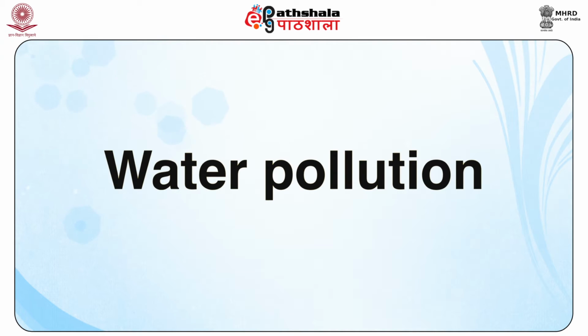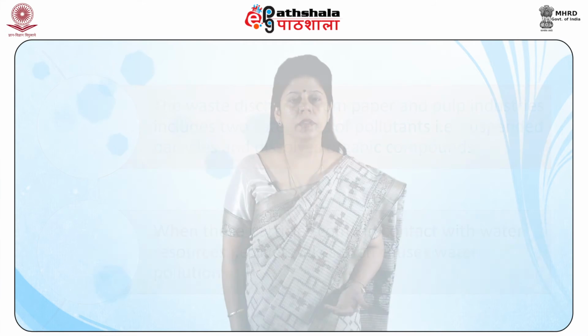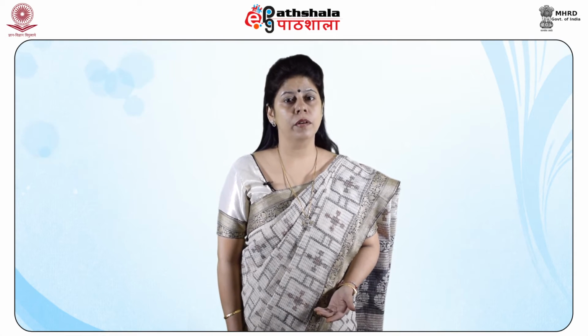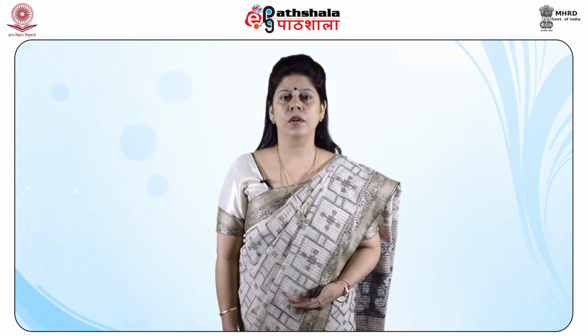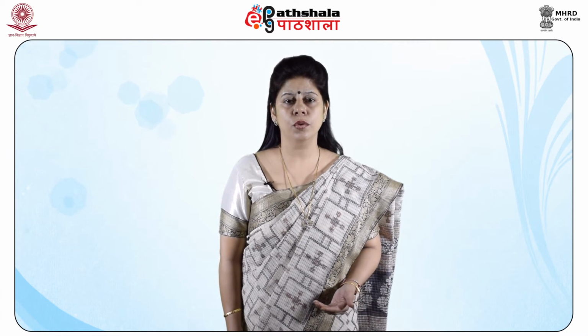The second problem is water pollution. The waste discharge from the paper and pulp industries includes two categories of pollutants, that is suspended particles and dissolved organic compounds. When these particles come in contact with water resources, that is rivers and lakes, they cause water pollution. The suspended matter present in the paper mills is in the form of particulates of wood, fiber, filling and coating material, whereas the organic pollutants, when acted on by microorganisms, are converted into inorganic compounds and reduce the oxygen level. Also, inorganic materials such as chlorates, chelating agents and transition metal compounds are included in the waste.